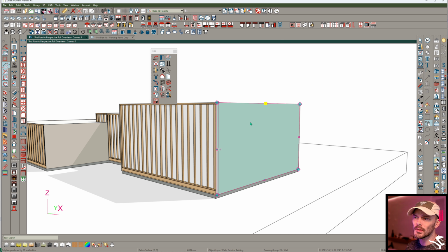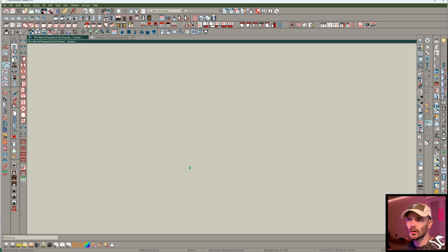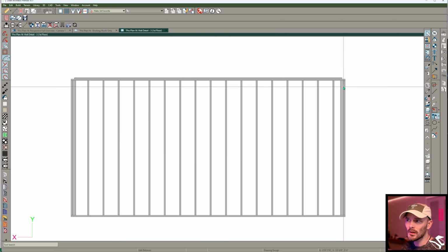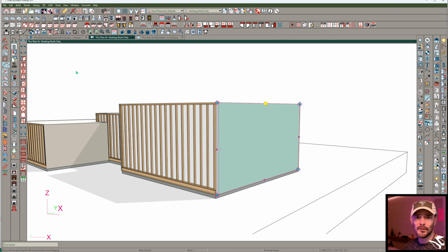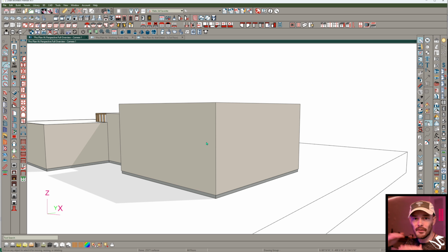And so what we're doing is taking this wall assembly. If we open up the CAD detail for this, I'm going to frame it while it's laying on the ground and then stand it up, put a little cleat in there to keep it standing until I've got an adjacent wall framed up that I stand up, and I connect the corners, and so forth, all right? Now, after I have that established, we have a uniform plate height. So our roof is designed by that plate height.